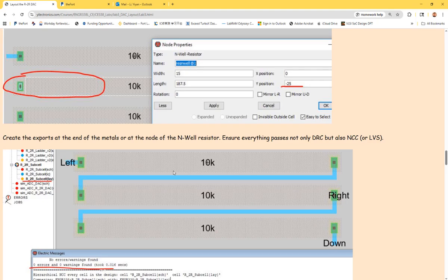So now we have metal 1, okay? And in order to connect to metal 3, just in case you are just making a little resistor on the chip, right? Eventually you want to probe it on the chip, see the resistance using a multimeter. So you do need a metal 1, and then directly on the top of metal 1, you need a via to metal 2, and then via to metal 3. So it's like resistors over here. You have metal 1, via, right? And eventually metal 3. Then you can probe it. That's how that works. Okay.